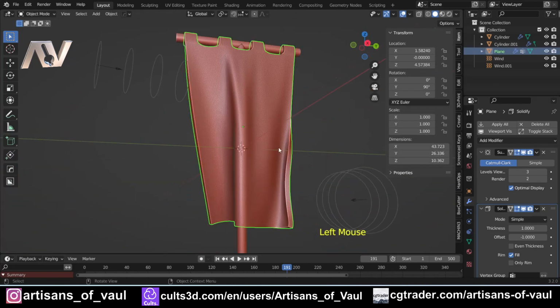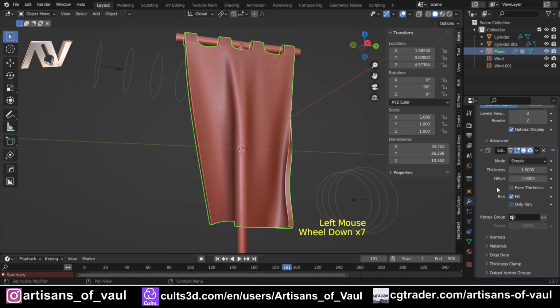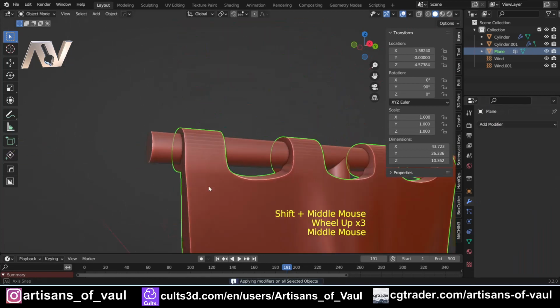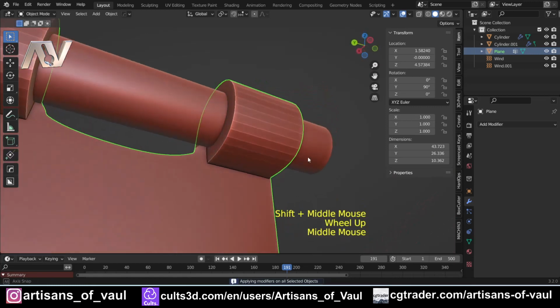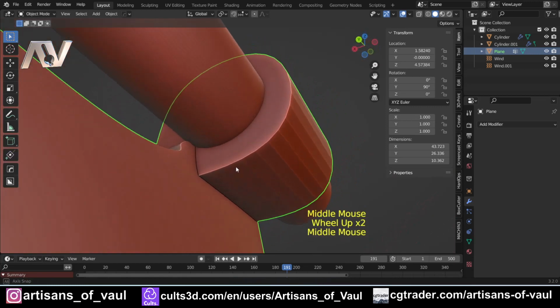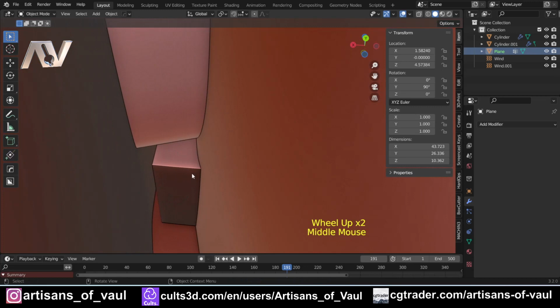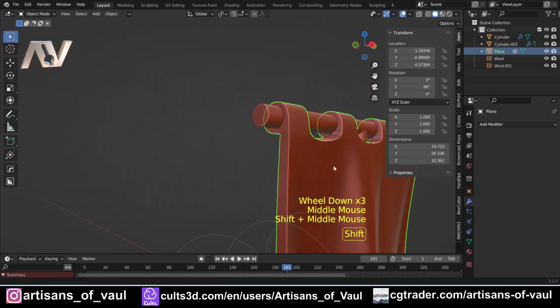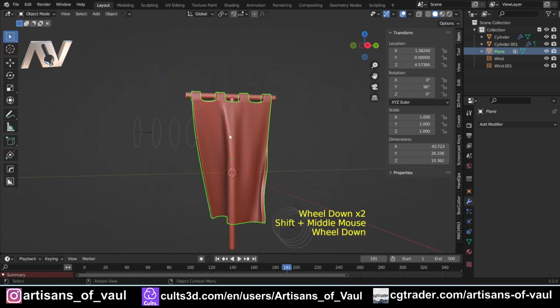So at this point, let's get this applied. So we've got our different bits here. We need to apply all of those, and then we've got this done. Now, I will say we've still got a problem to fix here. At the moment, these are still going inside. We've got what we'd refer to as intersecting faces, and this will stop this being a manifold object. So we do need to sort that.